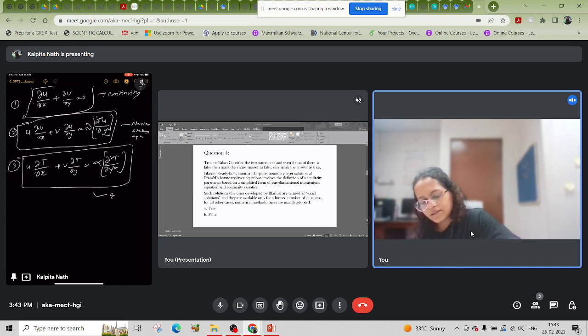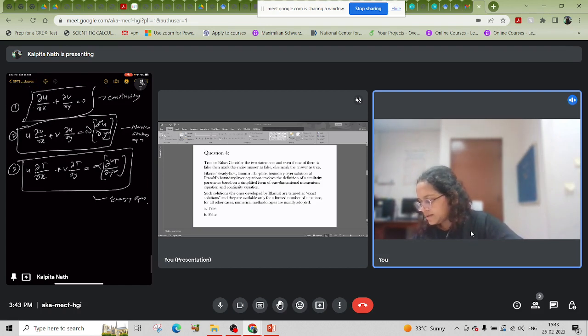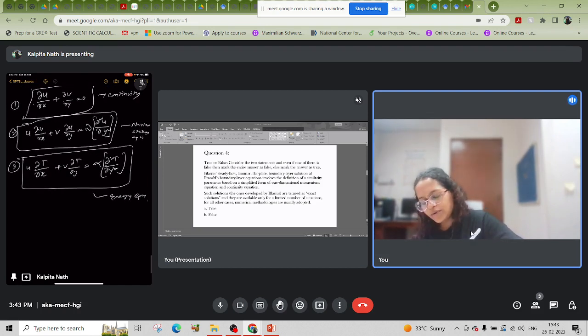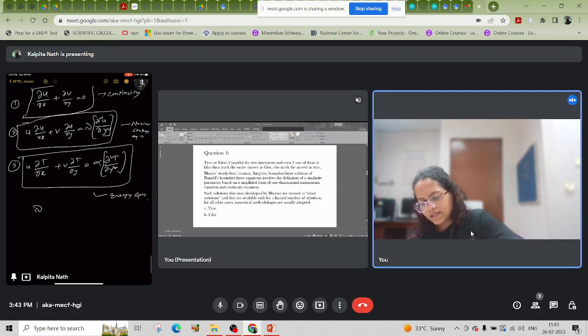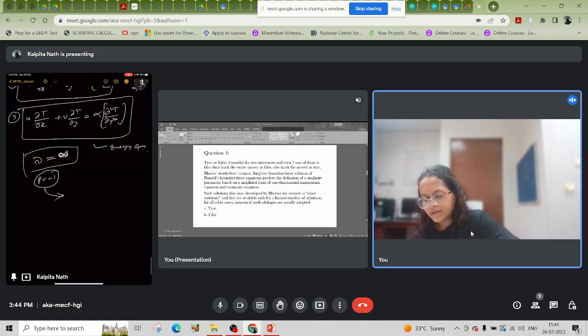This is the energy equation. These three equations are equal only when nu is equal to alpha. Then these three equations will be equal. So if nu is equal to alpha, that is, Prandtl number is equal to 1. So this Prandtl number 1, this was the idea.